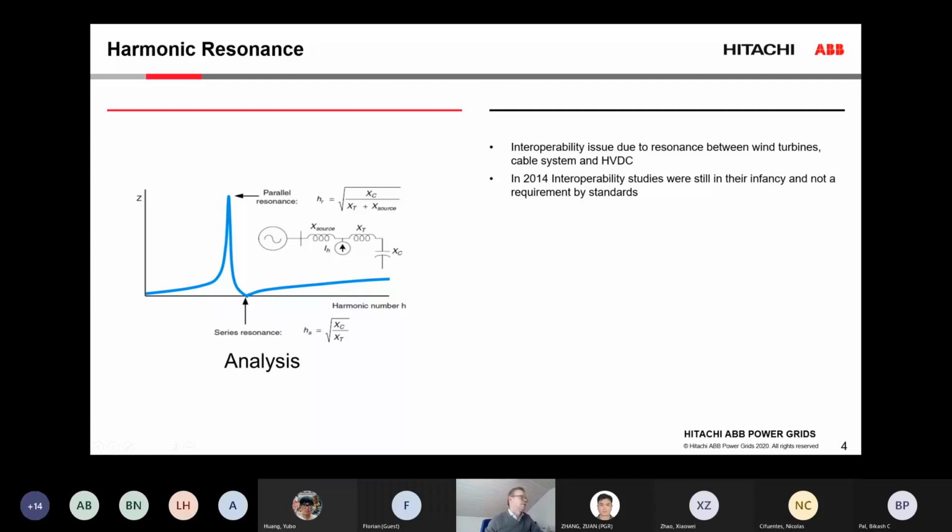But in principle, this type of figure still holds here. We can use the impedance response to predict resonance points. And when you run modal analysis, you would see that these resonances are visible also in the modal analysis results. You will calculate damping, and those dampings will be related here to the sharpness of those peaks and valleys.